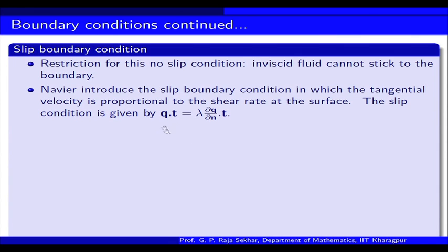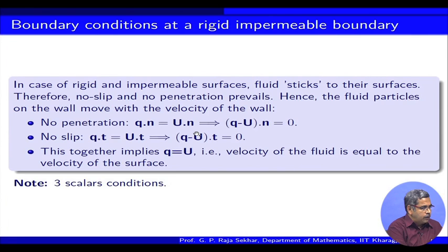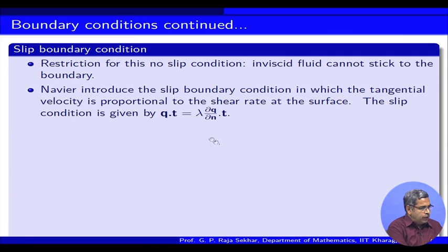The corresponding tangential velocity is no longer the way we have considered it, where the relative velocity is 0. It is not that. Okay. The kinematic condition is fine, the tangential one we are revisiting. What we are revisiting is that the tangential component is proportional to the shearing of the corresponding tangential component, and the proportionality constant is called lambda, which is the slip condition.